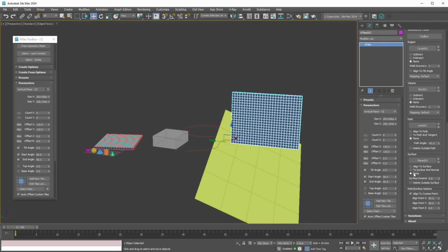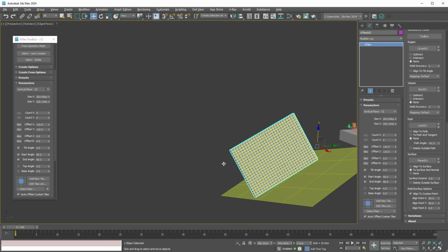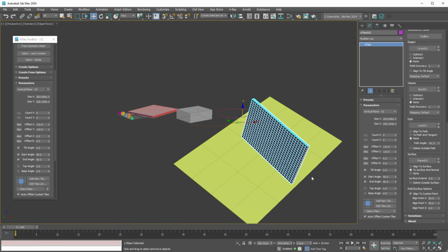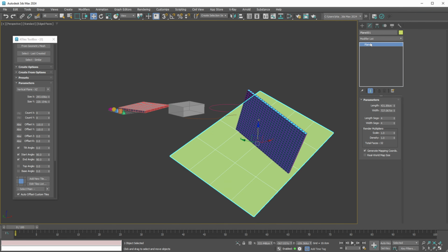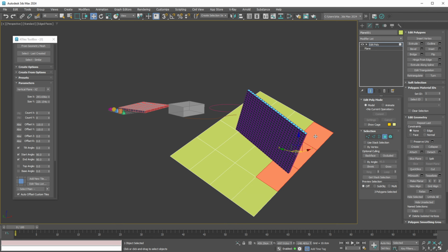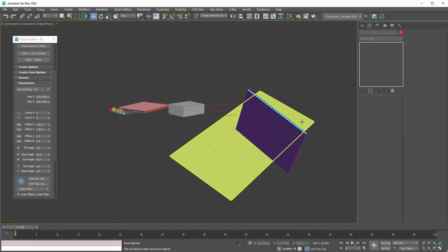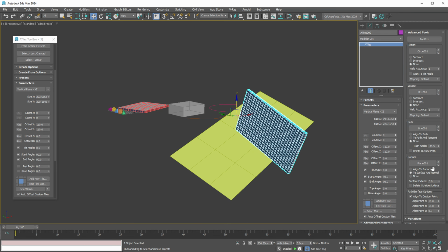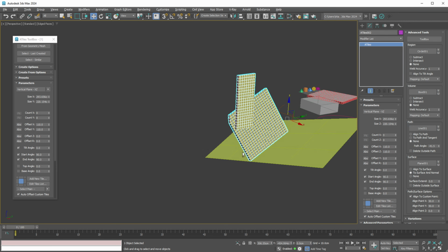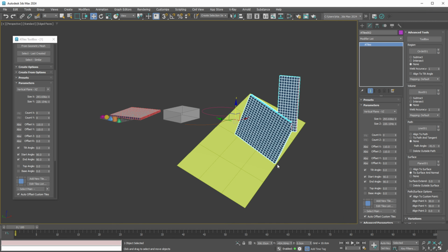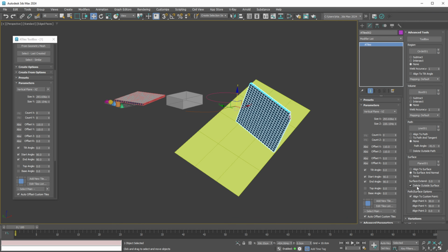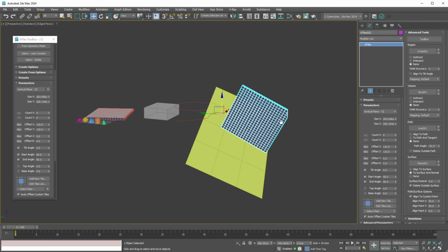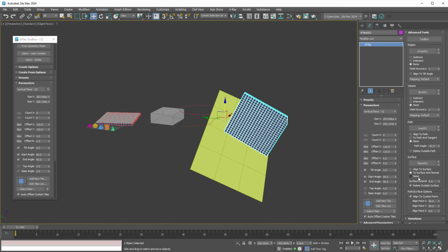One significant upgrade in this version of the plugin is the option to extend the surface effect. If we lack sufficient information about our geometry, we can still generate the surface intersection based on the projection of the selected surface. For instance, by updating the modified plane, we notice that some tiles are not aligned to the surface due to the absence of geometry beneath them. Choosing the Delete Outside the Surface option removes these tiles. However, by extending the surface with the new parameter, we gradually see our geometry be revealed and positioned correctly.